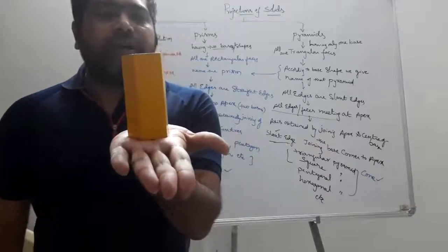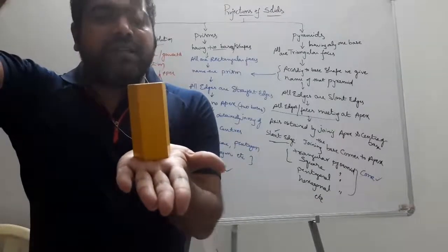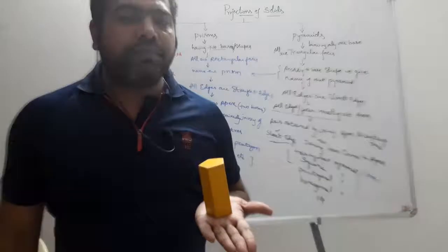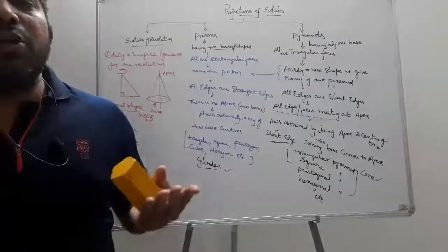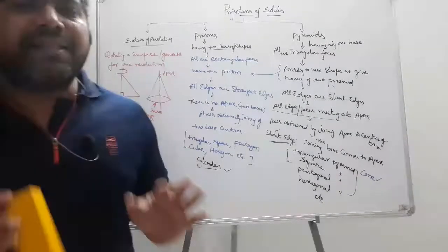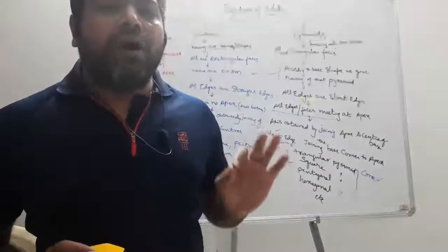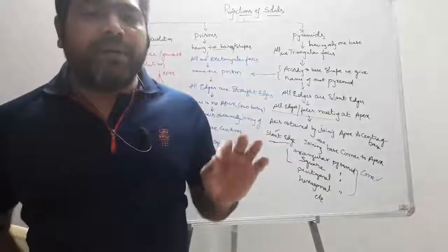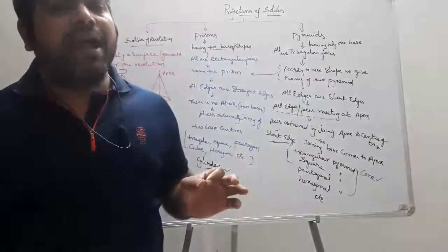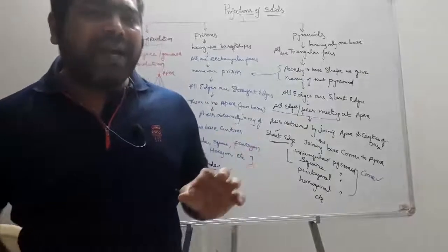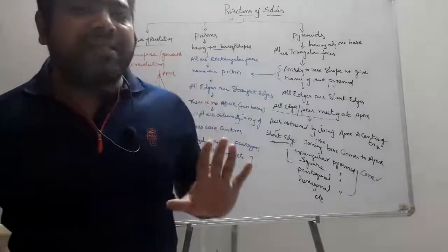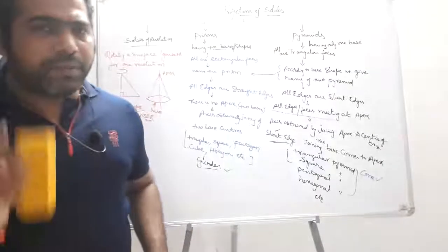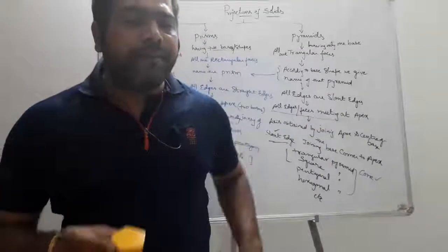Whenever your axis is perpendicular to HP, only then do we see the true shape of the solid from the top view. So the projection of solids completely depends on the axis inclination. Always remember that the axis is either inclined, or perpendicular to one reference plane and inclined to the other. So this is completely based on the axis inclination, which is very important. Let us see a simple problem for your understanding.